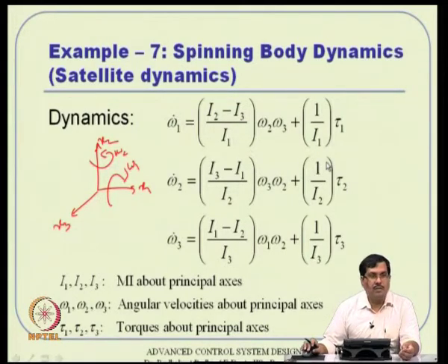So, these double integrator problems are also available, but that is only a linear expression. That may or may not be able to do the job, but the moment you talk about the full system dynamics, this is the equation you have to deal with. Linearized system dynamics or a linear control system will not be able to do the job, because this entire term will drop out. You will not even see it there. These are the various definitions: moments of inertia about the principal axes, angular velocities, and the principal torques given for control purposes.